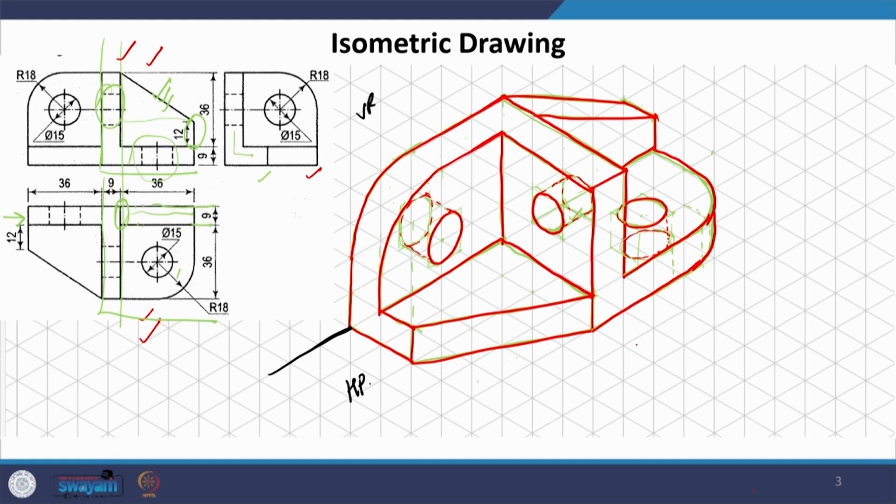This is what we will arrive at, and you can check it again. No lines should be missing, no surfaces. Every line has a meaning, like this one, which means that this surface is at the same level, but this one is not, which is what we see here. This is at the same level, but this is not, this is a slope.